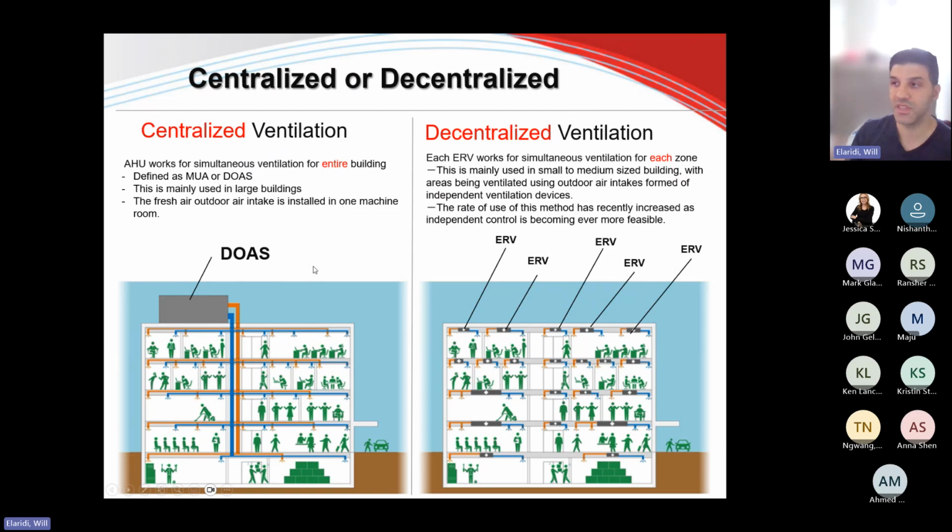Or sometimes it does pressurization in a corridor and allows the infiltration of fresh air to go into each suite. Basically, this would prevent any odors that would be present in the hallways caused by cooking, for example, and other types of chemicals that could be built up within the suite. By pressurizing the corridors, you're able to push those smells to stay in the suites and rely on the bathroom exhaust to do all the exhausting that way.